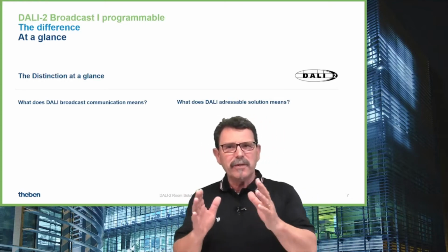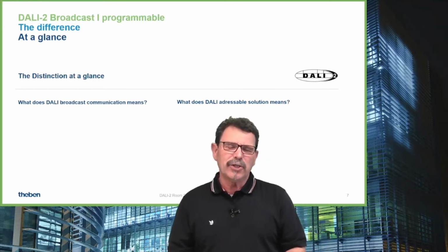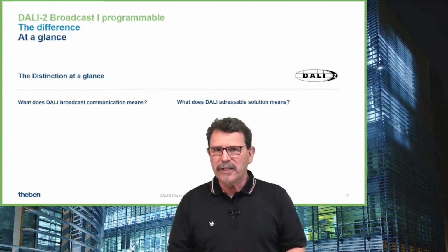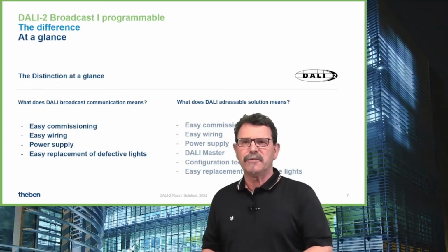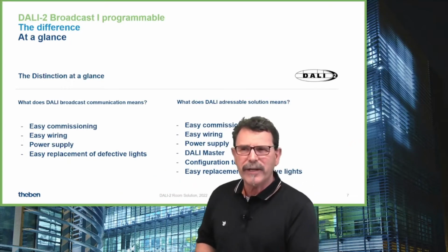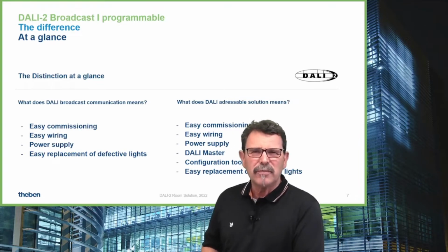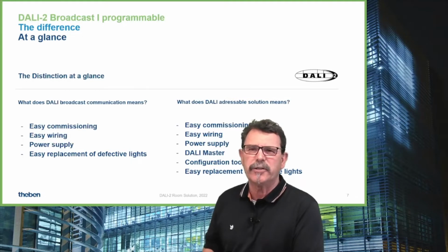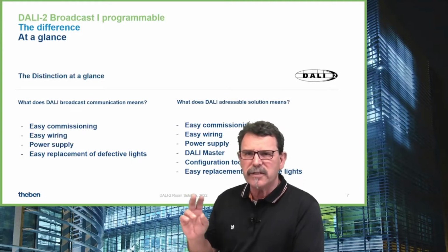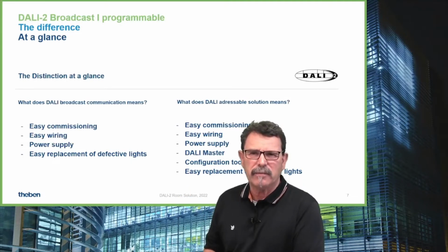When it comes to the addressable solutions of DALI, this is slightly different in terms of the commissioning and in terms of the wiring. In terms of wiring, it is the same. You just link it to the DALI light and the DALI communication wires. You need, in both cases, a power supply. Just all in all, overall.